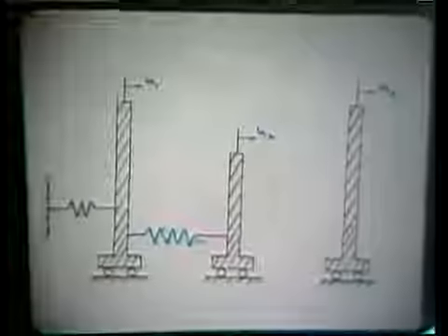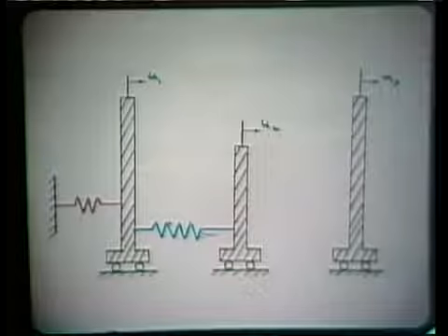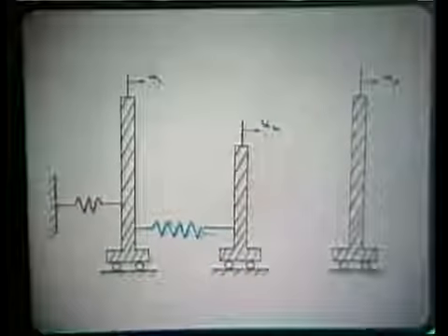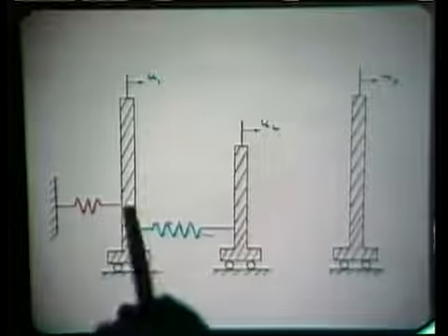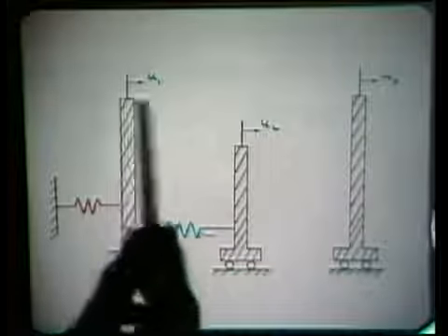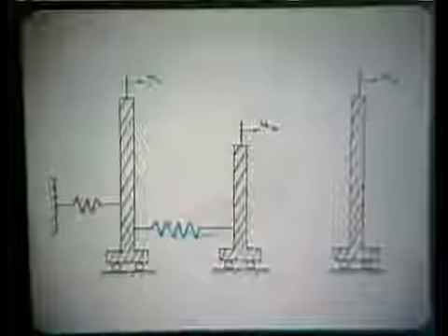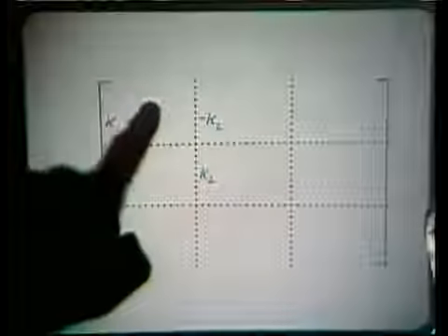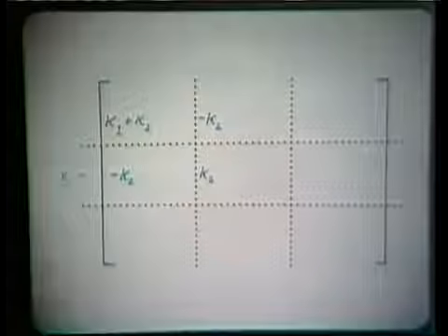So this is the stiffness matrix that governs the equilibrium of this physical system. Notice that this second spring couples into U1 and U2, and therefore we have added these blue elements corresponding to the second spring into degrees of freedom 1 and 2.